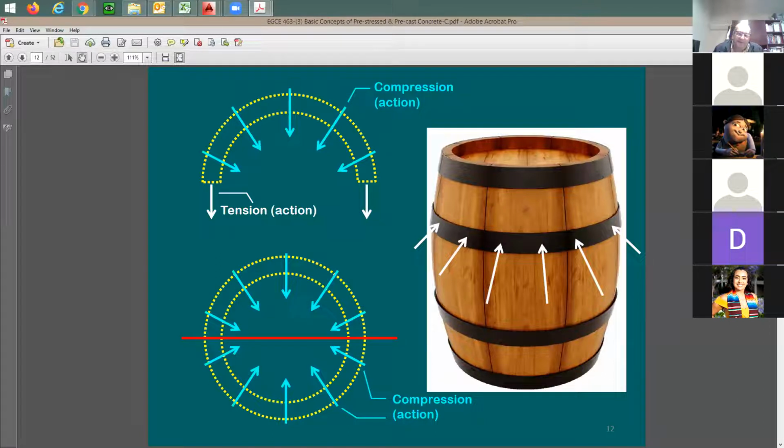This is happening in concrete design. In concrete design, the tension is not going to be triggered in the rebars unless the section starts to crack. In our case here in pre-stressed, the beam is already stressed before you even start to put it to use. You have lots of pressure in there. I mean, this is the way it works.